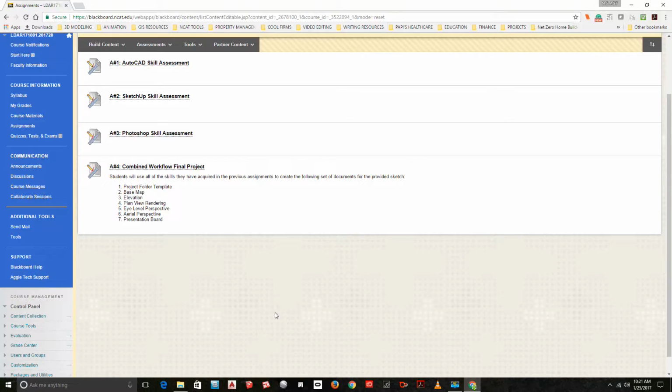However, I'm going to express to you a way to generate a base map using SketchUp, tracing a SketchUp image and bringing it back into AutoCAD because it allows you to generate contours in this way. If you're lucky enough to be working in a municipality, or doing work for a municipality, that has a decent GIS infrastructure, sometimes you can download DWG files and also shape files to generate AutoCAD base maps for yourself automatically.